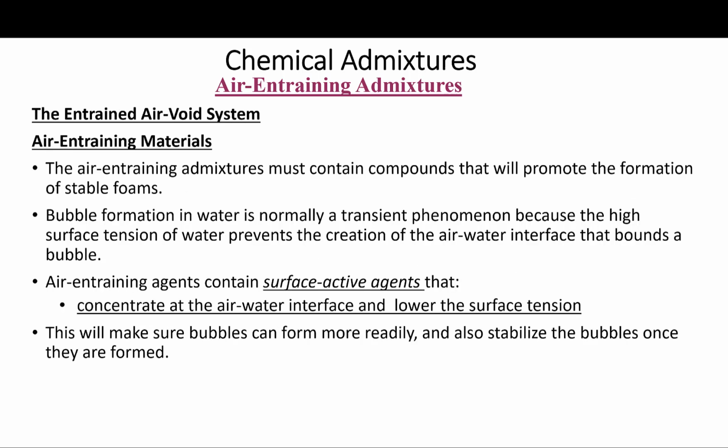I'm going too fast. Let me go back. Okay, let's talk about the air-entraining materials. As can be followed from the preceding discussion, air-entraining admixtures must contain compounds that will promote the formation of stable foams within the paste. Bubble formation in water is normally a transient phenomenon because the high surface tension of water opposes the creation of an air-water interface that bounds a bubble. So they're not stable with water alone.